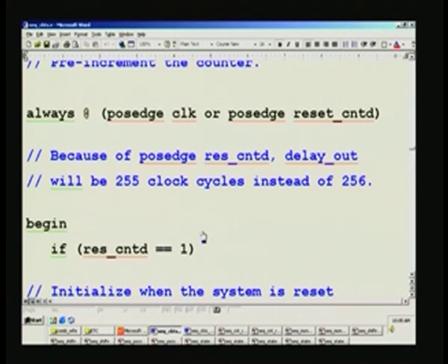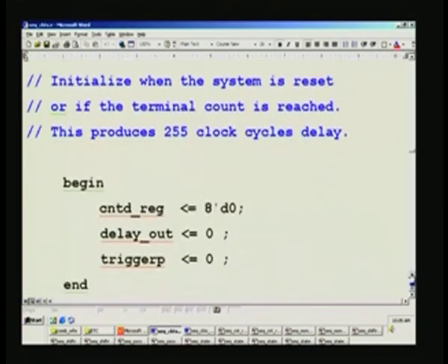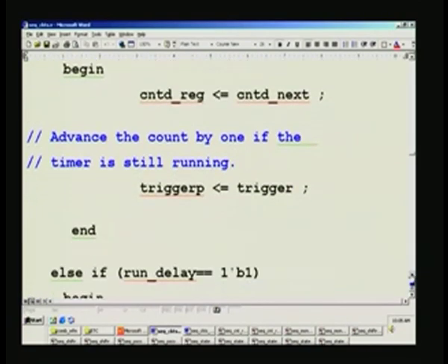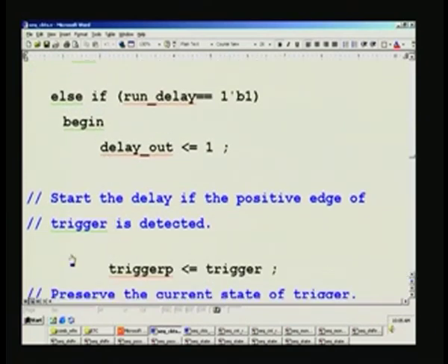In the earlier way of representation, the power on reset was dealt with here, and the actual counter reaching 255 was dealt with somewhere in between. So it added one more else if, thereby slowing the system, and also instead of the 255 set point we got 256.